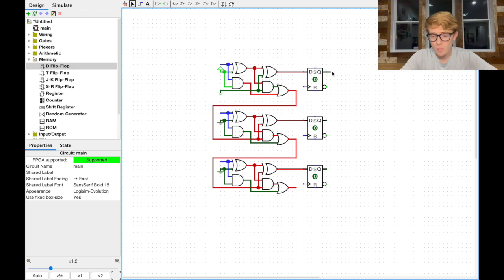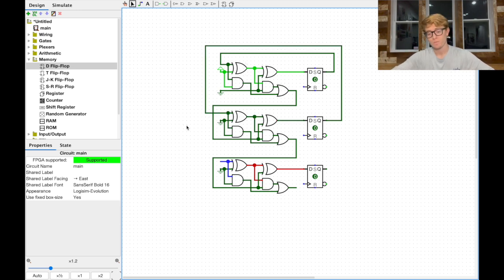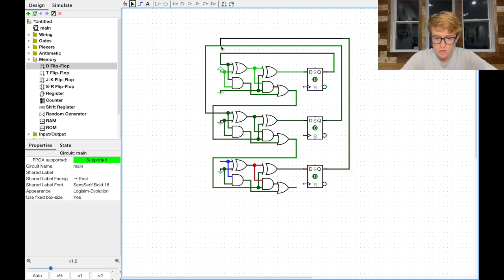And now what's gonna happen is the output from each of the DFFs is gonna route over to its corresponding input pin on each full adder. So this is creating feedback. And this is what's gonna allow us to save our state and continue counting. This concept of feedback is very important. This is how we use DFFs to create more complex circuits and sequential logic. So now that we have this feedback, we can actually increment the value. The value is constantly being updated as D propagates to Q on each clock cycle.